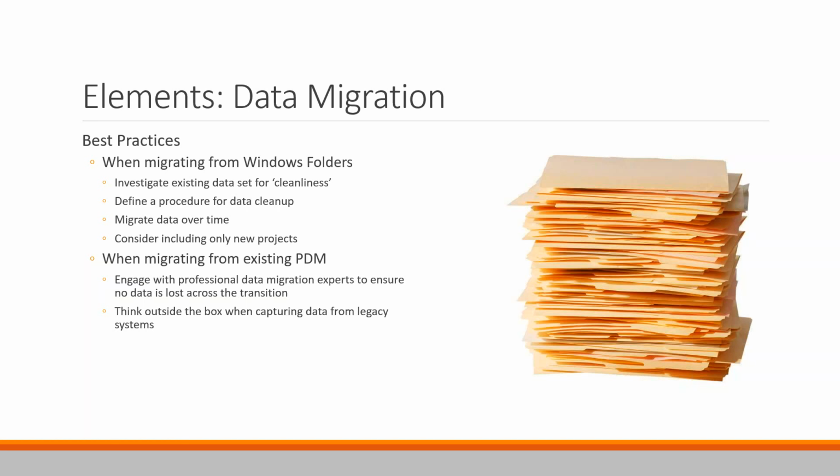And so if you've got any sort of relational bit of information where you need to capture that and be able to search and see relationships and see information about records, you could potentially use items in Vault to capture that data, even if you have no need to manage bills of material. Records, independent of files, linked together for informational purposes. Items are a great use for that.